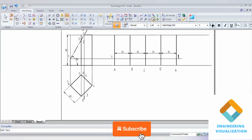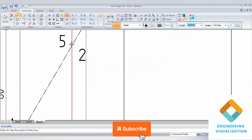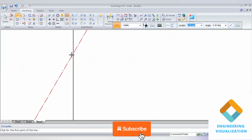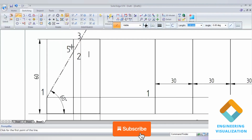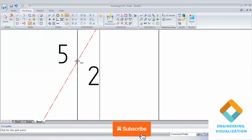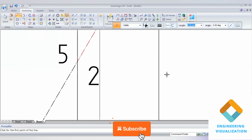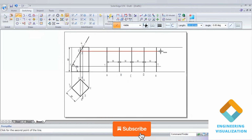We get point 1 on the vertical edge A. On the vertical edge B we have point number 2, and that we can also project. Points 2 and 5 are on the same height, but I'm not getting the intersection here, so I can use the split command to get the exact point. I'll go to the split command and split it exactly where the section plane is cutting. Now I'm getting the exact point. From here I'm going to project it.